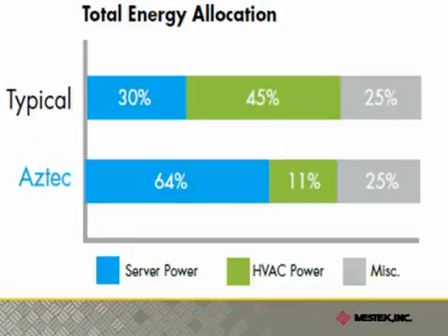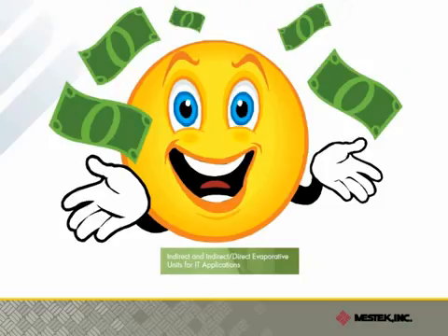Now, the amount of energy required for HVAC drops dramatically, and the whole PUE number shifts to something more like 1.5 or even lower. The data center operator can either reduce his overall building demand and save capital and operational costs, or shift more of the available electrical energy into the servers and increase his data processing capacity by more than double from the same size building. Either way, the owner wins: lower capital costs or more revenue producing servers from the same amount of total power.